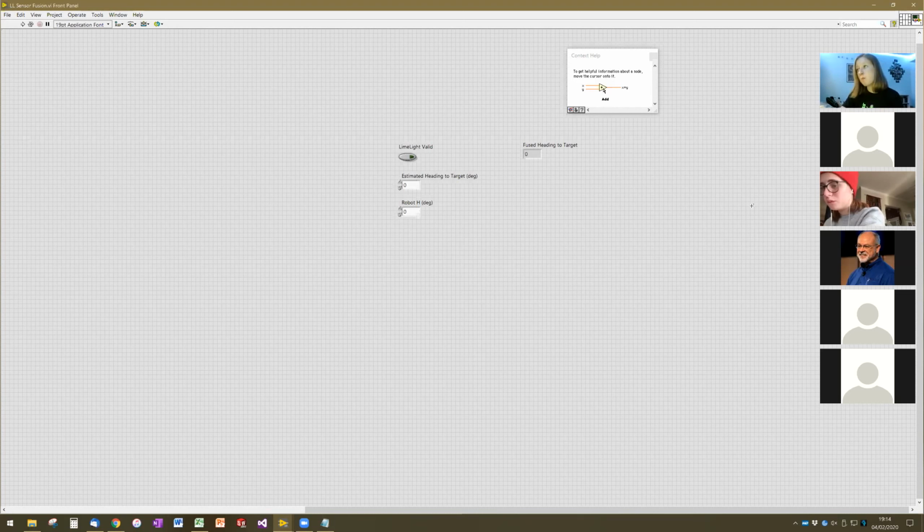So that's why when we turned on the temperature calibration, a lot of our gyroscope drift problems went away. There's another little nuance there. Doing the temperature calibration on the IMUs improves the accuracy even if that particular IMU isn't affected by temperature. The reason is there is a periodic calibration that the robot runs on the IMU, but it's only enabled if the calibration has been run once.